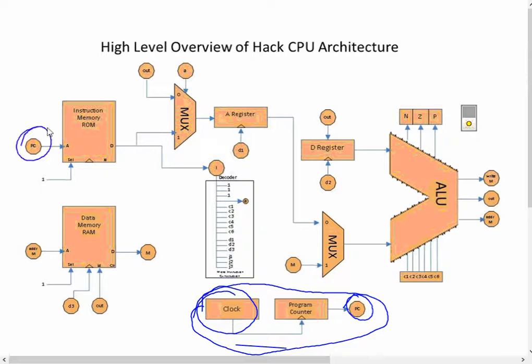It's going to send that number to the ROM memory, the instruction memory, because that number is going to be the address of the instruction I want to execute. So maybe it's going to send the number 5, right? Well, maybe in this particular case, the number 5 represents an instruction in the instruction ROM memory, and that instruction, because I provided the address, is now going to send the data out to be decoded and then sent into processing for the ALU.